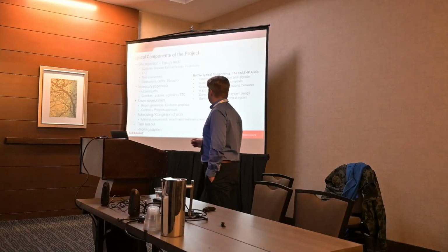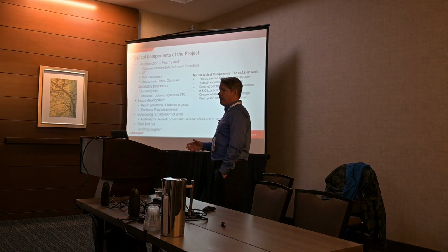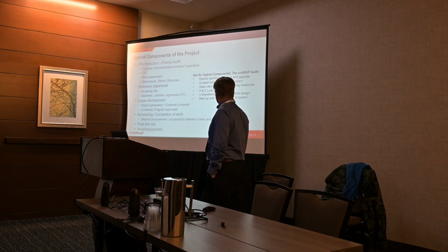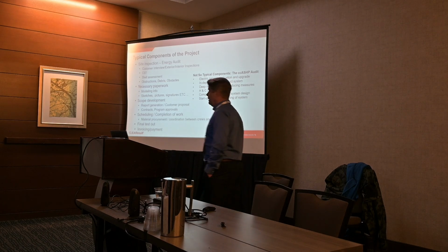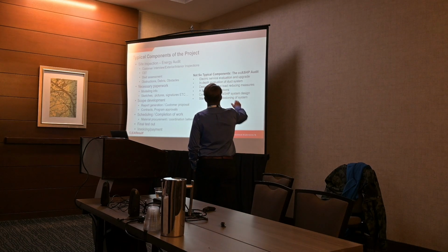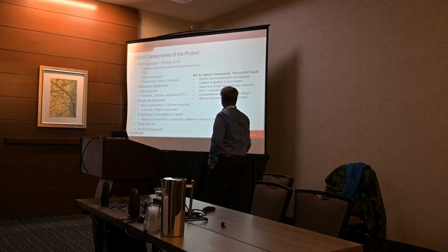If this house doesn't have an air conditioning system there already, it most likely doesn't have the amount of power it needs to install air source heat pumps, right? They need the same thing. They need a 200 amp service. So we have to take a look at that, see what they have, and that might become part of the upgrades that we have to talk about.